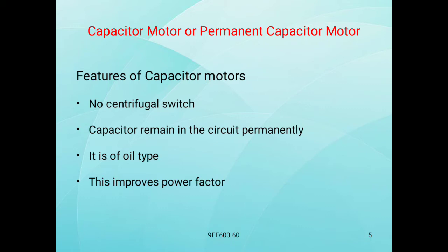So on starting, for the starting purpose the capacitor is electrolytic, for running purpose it is of oil type capacitor. So there it also improves the power factor at the starting time. Here also it improves the power factor.